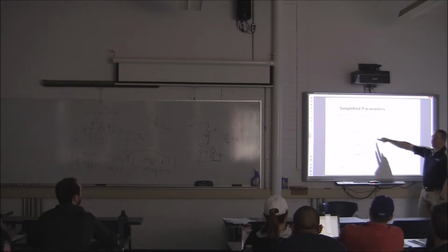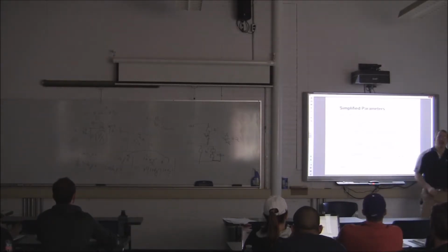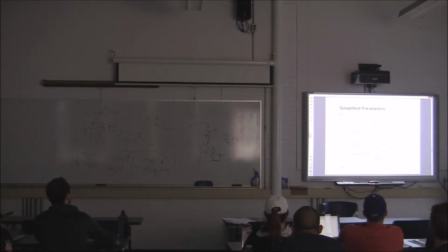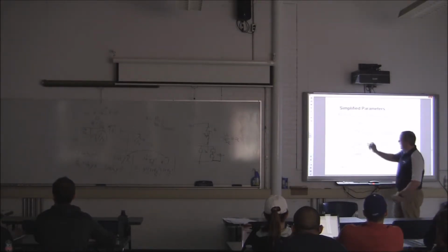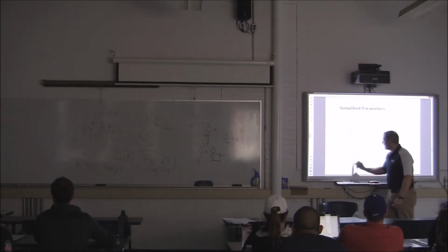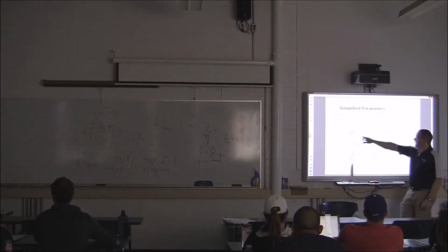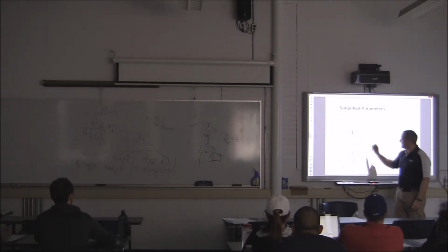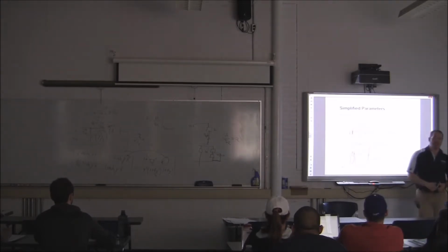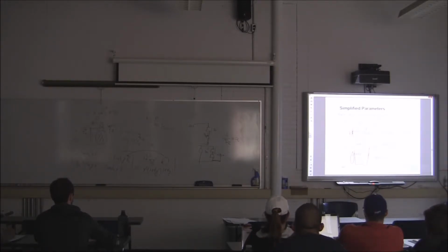Remember, if we use the T equivalent, we'd be using the ZL, but this is the pi equivalent, so that's why it needs to be adjusted with those hyperbolic sines and the gamma L's to make it equivalent. That's my Z, that's my Y, or my Y prime. And the biggest advantage is you've got a Z and a Y over 2. These two terms fall out of our original equations just by multiplying by the per unit length, and we have what's called a scaling factor. It scales the magnitude and it phase shifts the result. That's what ends up happening.